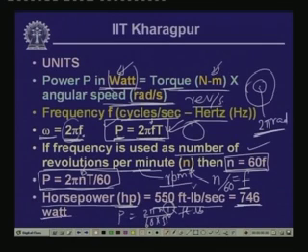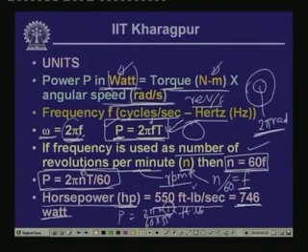So, if we use this relationship, if the power of a motor is defined in terms of horsepower, we can convert that in terms of watt, and we can use our relationship that watt is equal to Newton meter times torque multiplied by the radian per second as the frequency or the angular speed. So, this is helpful in relating the transmitted power and the torque, and so when we like to find out the diameter of a shaft which is necessary for transmitting power from one device to the other without exceeding the level of stress, then first we compute the amount of twisting moment that is getting generated in that shaft for transmitting that amount of